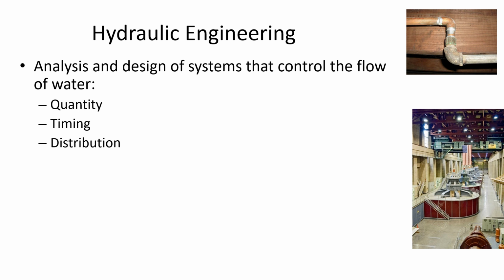Because that's ultimately what the hydraulic engineer is sizing when you are doing closed conduit flow, is the size of the pipe that's required. And you'd maybe just say, well, why not make it just a really big pipe? Because then it doesn't matter if there's a lot of flow or a little flow, you're always going to get enough pressure downstream.